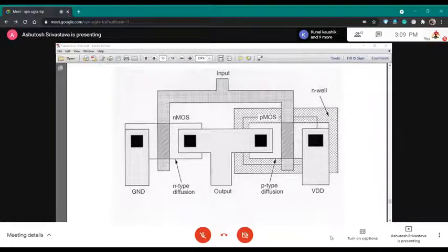as well as how you scale down the transistor. There are two major ways that we have already talked about: constant field and constant voltage. And there's another approach which takes advantage of both these approaches, namely constant field and constant voltage scaling. And what you get is a generalized scale. And there shall be some numericals based on that in your exam too. So that's a hint.